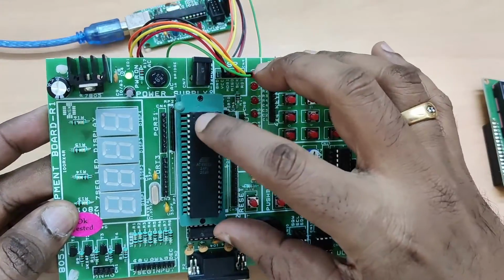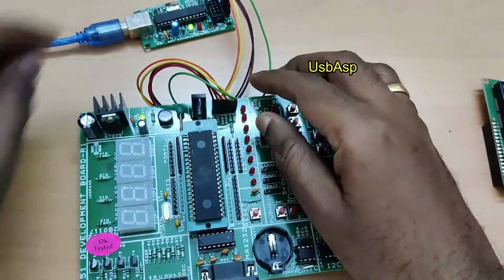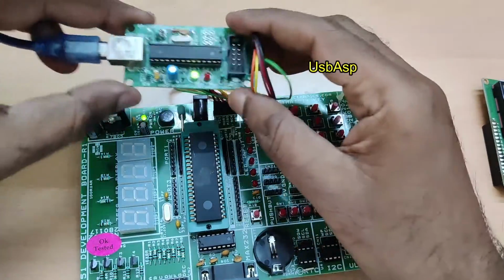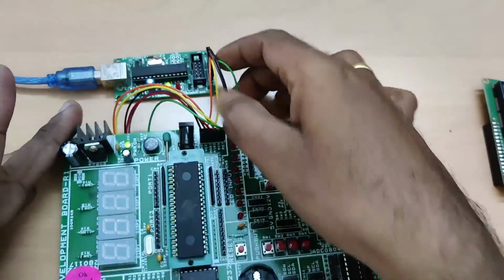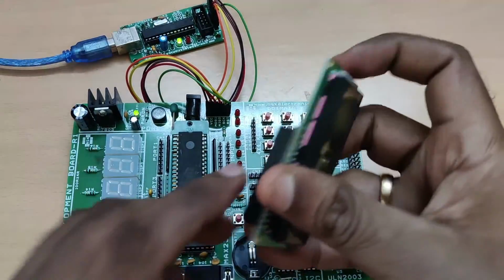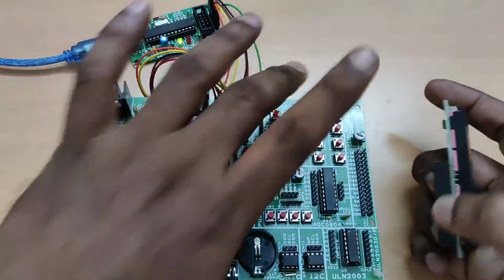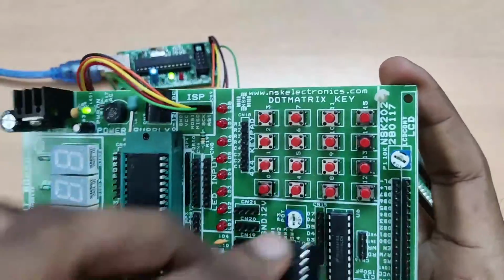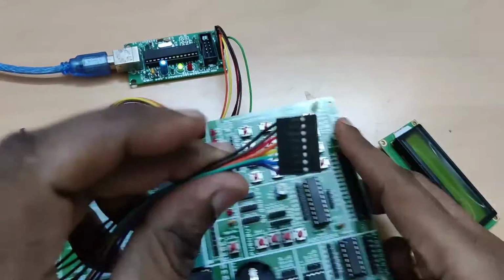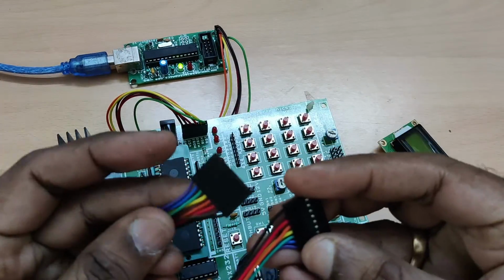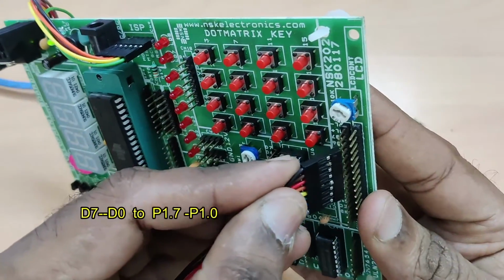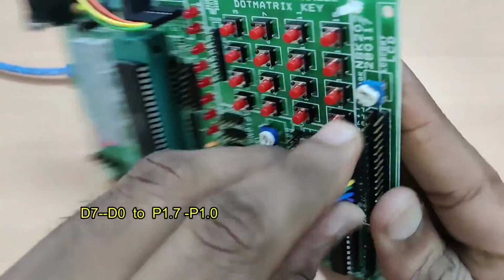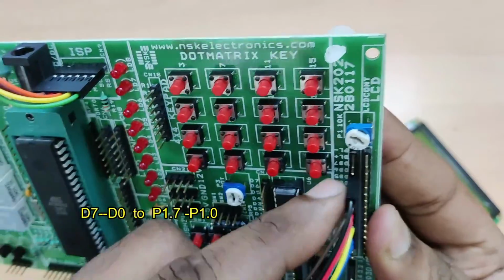for control. This is the development board we will be using in this project, and the AVRdude is connected to the ISP connector. LCD can be plugged to the Berg sticks, to the inner pins. Let us do the connection first. We'll be using this type of 8-way jumper wire for connecting the data bus. Data bus we are using is port 1.